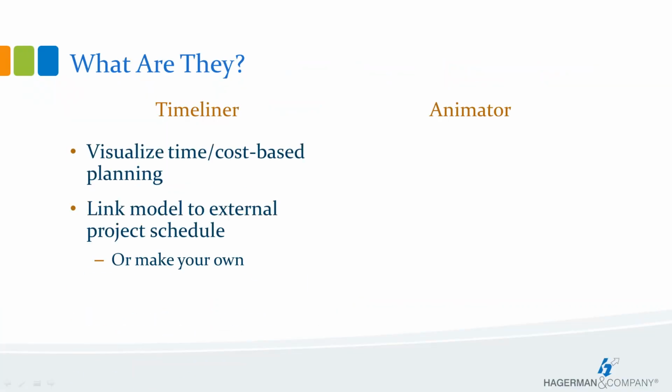Well, the Timeliner is a tool that will add schedule simulation to Navisworks. It imports schedules from a variety of sources. You could bring in a schedule from Microsoft Project. I believe another application that works with Navisworks is Primavera, and you can also bring in a CSV file to get started there. And you can connect tasks in those schedules with objects in the model to create a simulation.